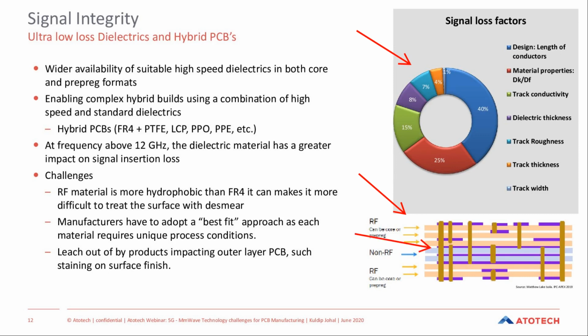materials in the center. And what this poses is challenges for the PCB supplier in terms of your desmear process. Now you have to have hole roughening that is sufficient to get good adhesion of the electroless copper without any blistering and with good coverage, and ensure that you are roughening both the ultra low loss materials and the standard materials. So again, it poses more challenges.